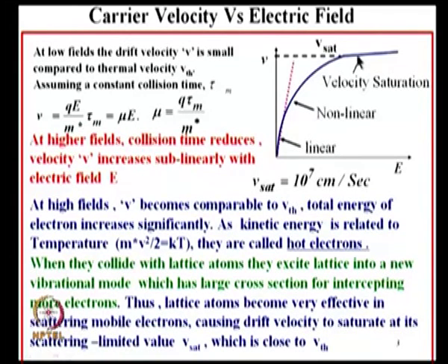So, whatever velocity is acquired is very close to the thermal velocity, which is the limiting velocity of the electrons. It can't go beyond that, because the entire thing is absorbed by the lattice. Okay. So, this is the principle of velocity saturation in basic semiconductor devices. This discussion comes up; for completeness' sake, I just brought this in.